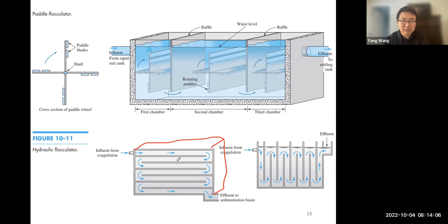But within this reservoir, you have these horizontal baffles, horizontal channels, so that the water is constrained to flow from the top, and then go through these again, and eventually to the end. Okay, and then we can also have baffled channels that look like this, right? The water has to go again, and then going to here.